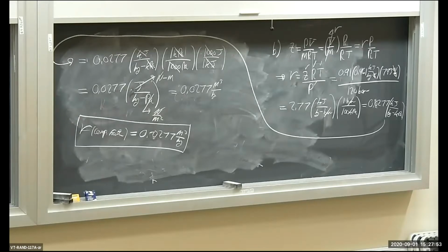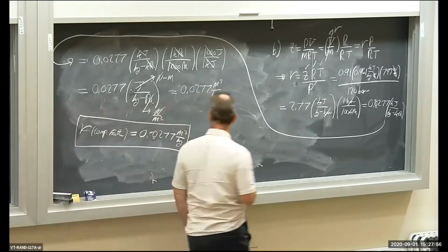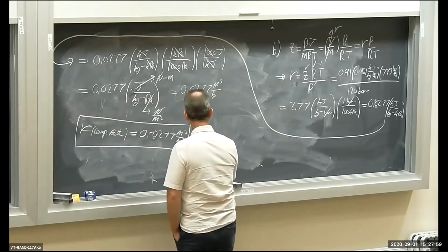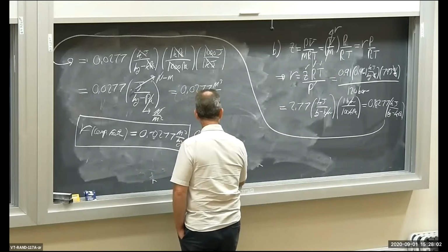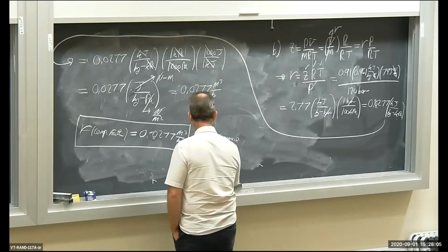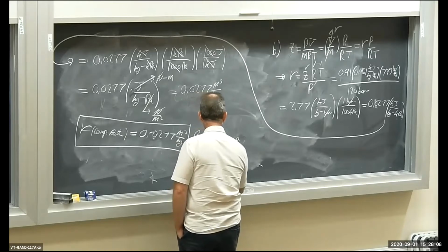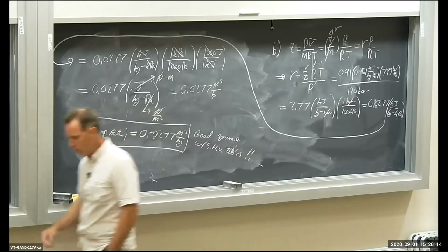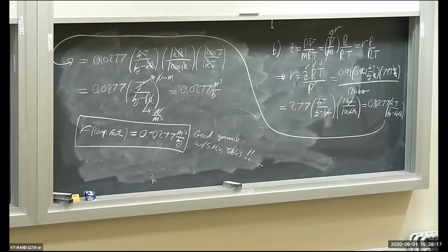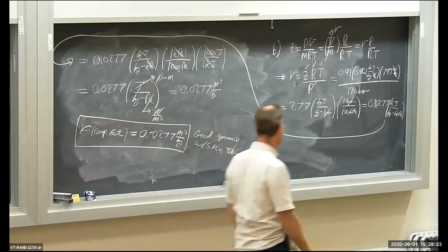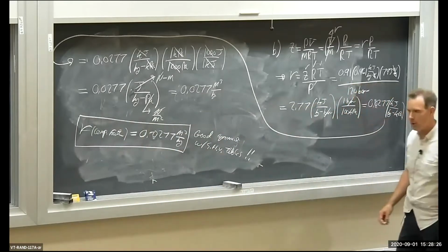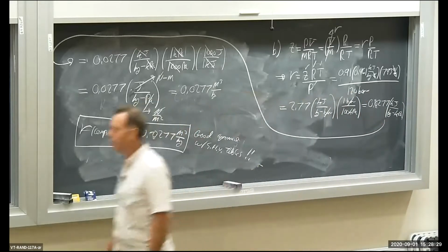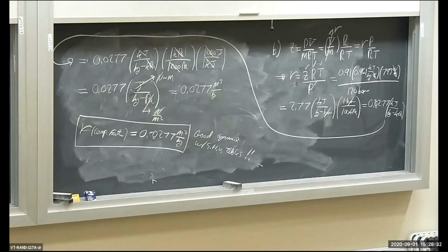Okay? So the compressibility factor approach actually did pretty good. Good agreement with superheated vapor tables. So if you want to calculate some quantities for a gas, you can either use superheated vapor tables or you can use the compressibility factor and the compressibility chart. Okay? Now we're going to finish up part Z, which is assuming the ideal gas law and cranking away. But I'm going to take a break for a second.